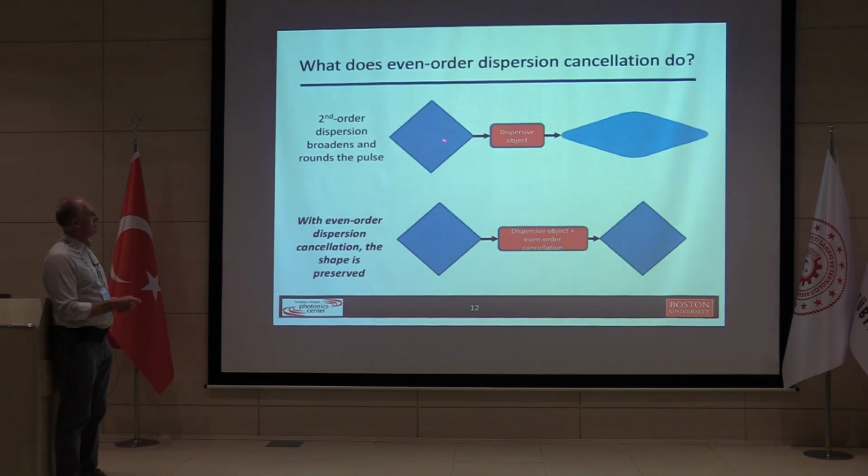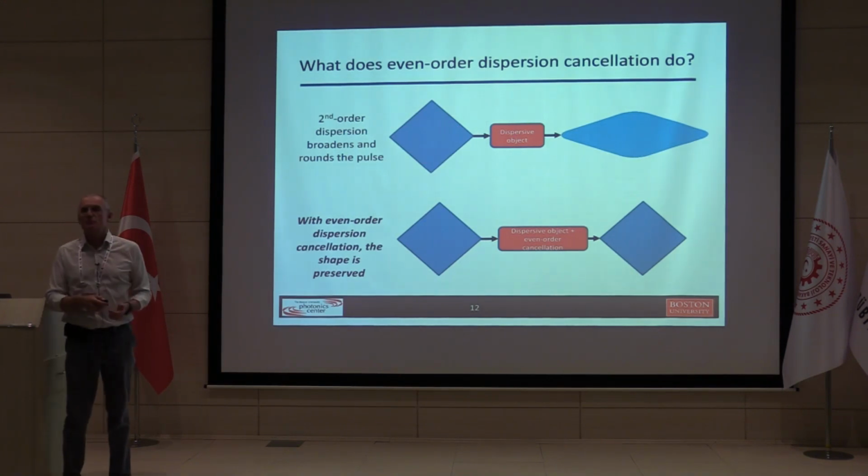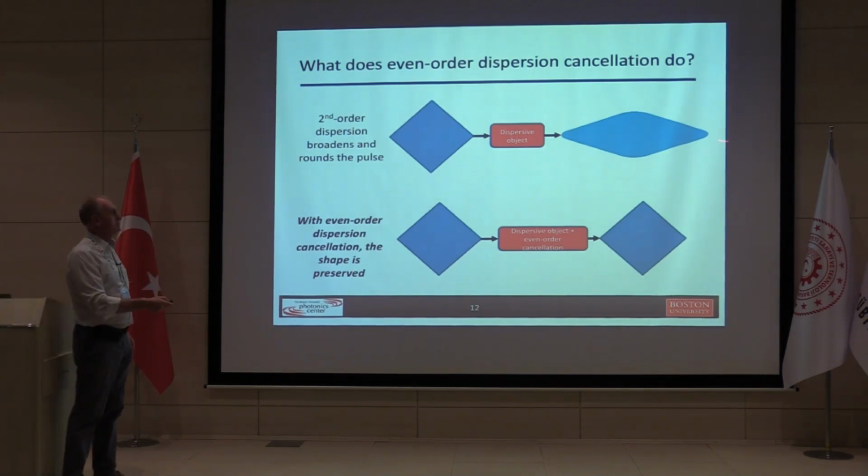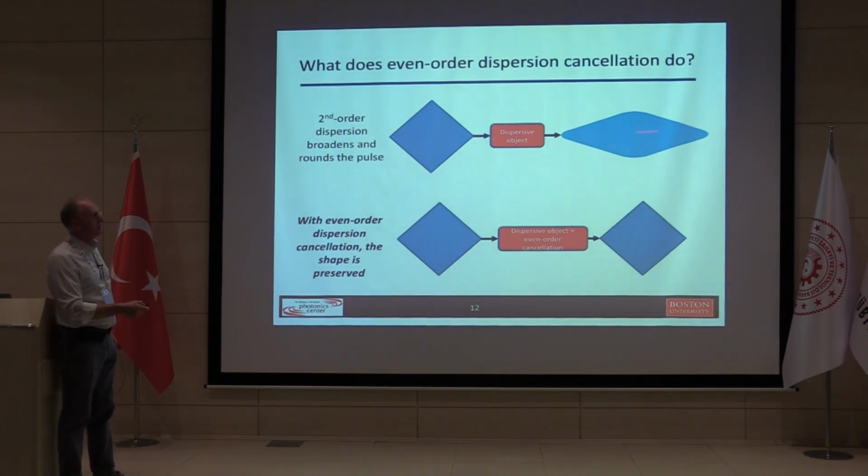In conventional interferometry, to get as good a group delay resolution as possible, you have to put in as broad a spectrum as possible. When you have a broad spectrum going into the object, you experience more dispersion. The broader the spectrum, the greater the dispersion. Then your envelope is spreading and you reduce the accuracy of measuring the center of it.